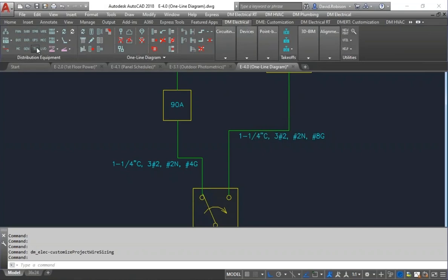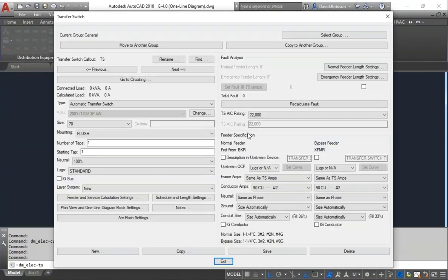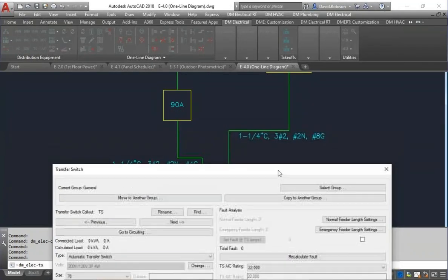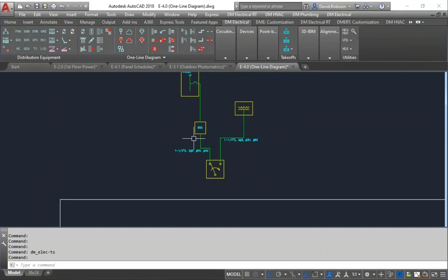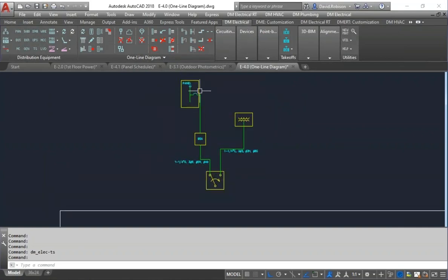So the question again then becomes, why are those different? You can see on the right it's connected to a transformer. On the left, it's connected to this breaker and then to this panel. So on the right, it's using the 102, the service ground sizing, and on the left, it's using the equipment grounding.